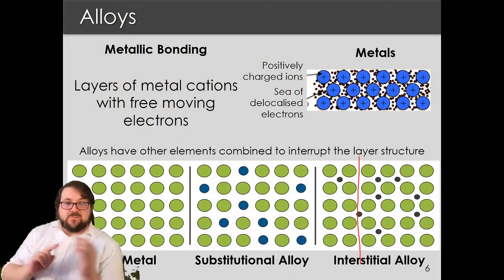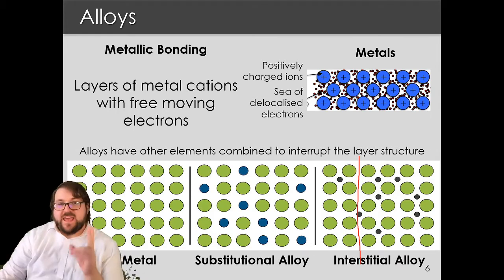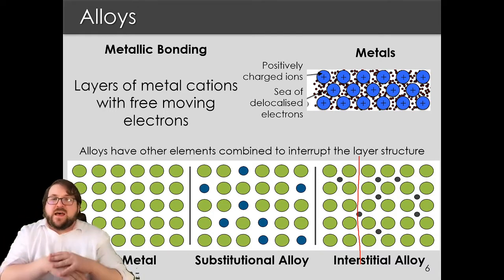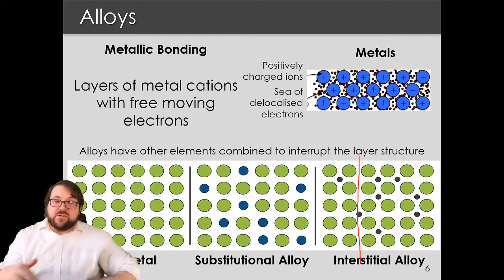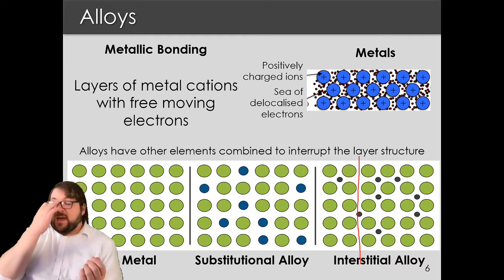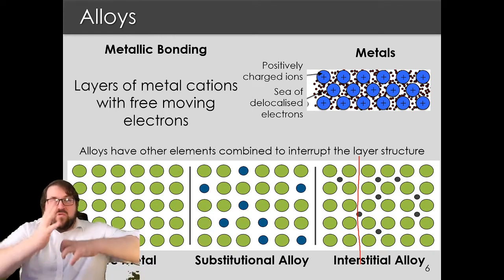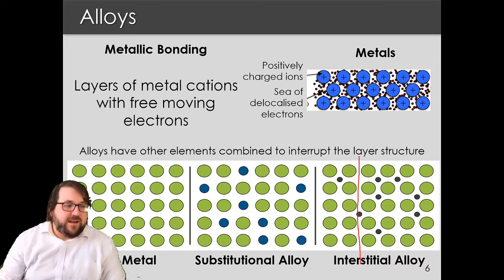Great, so we've had that going for a little while, and we're basically looking at the aluminium can being like the pure metal behind me. So there we've got the regular structure of the aluminium atoms, and what the gallium's going to do is slowly get between those layers and start basically either substituting or being interstitial in the original lattice. Now, you can imagine that what that means is that the lattice is going to have to move out of the way of the gallium atoms to allow them in. So let's have a look at what that looks like when that happens.